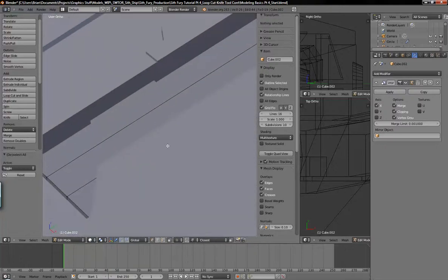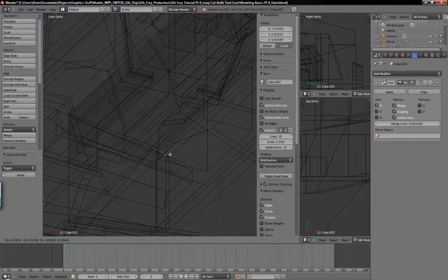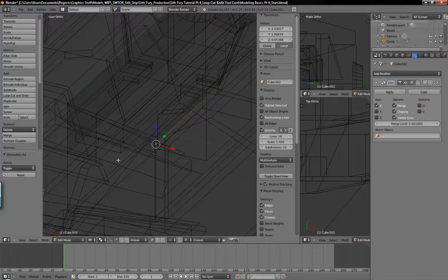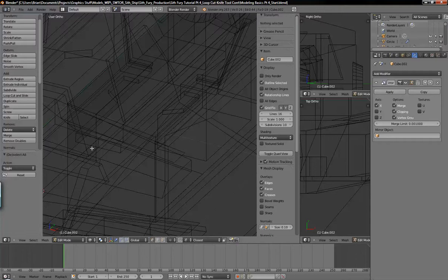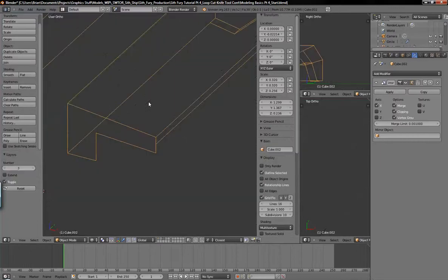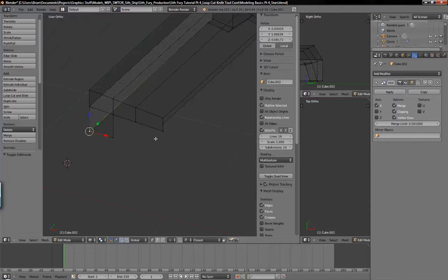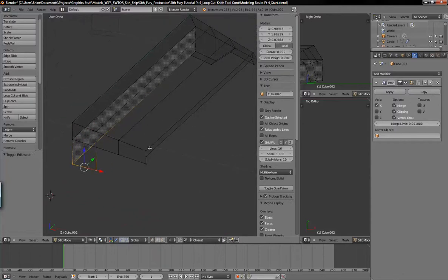And we can actually go around to this back side and see how much of that we need. You can see that's not connected there, but let's see what we need here. Let's do this. Go tab in edit mode. I want to move this to layer 3. Go to layer 3, and we only need just basically this thickness here. We can get rid of this. Delete those vertices down there.